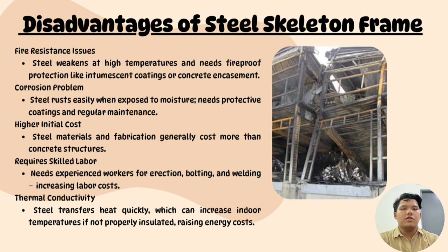Disadvantages of the steel skeleton frame: fire resistance issue. Steel is weak at high temperature and needs fireproof protection like intumescent coating or concrete encasement. Next one is the corrosion problem. Steel rusts easily when it is exposed to moisture. It needs protective coating and regular maintenance.